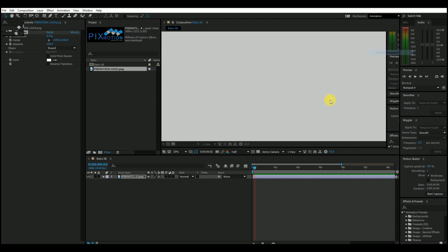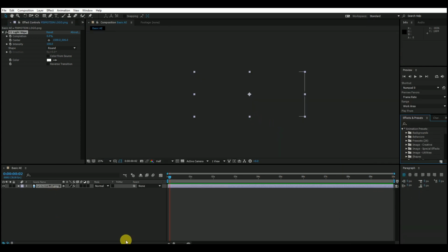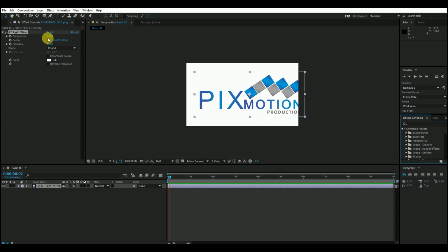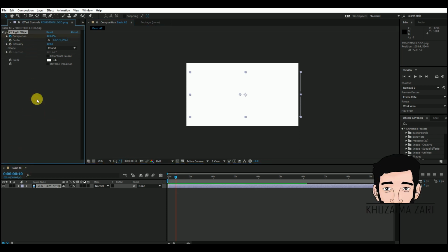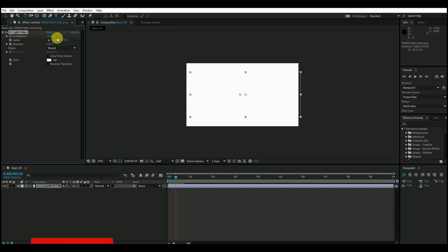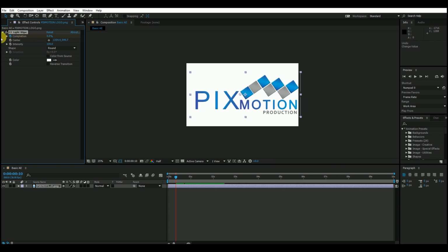Also, as we did earlier, put a keyframe here. Make this 100%. Okay, and move forward. Now, if you hold shift on your keyboard and press page down, you will go 10 frames forward. Because when you press page down, you will go only one frame forward. With the shift, you will go 10 frames forward. Okay, and now we put the 100% key at the start, and after 10 frames we will put a keyframe of 0% here, because for the transition effect we used, we want it to end, right? So make sure you put 0% after 10 frames.